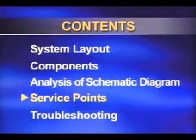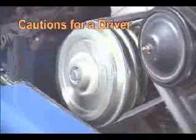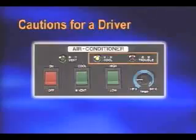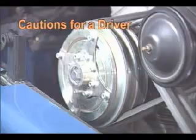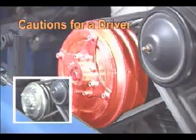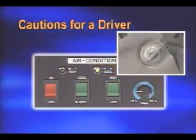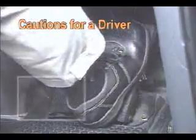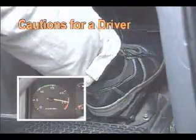Next, we would like to explain the service points. First of all, we would like to remind the drivers of the following cautions. When the warning lamp turns on, you must turn off the air conditioner, or the magnetic clutch may be damaged due to repeated on and off magnetic clutch operation. When the air conditioner is turned on immediately after the engine starts, do not race the engine in idle state, nor accelerate suddenly, or the compressor may be damaged.